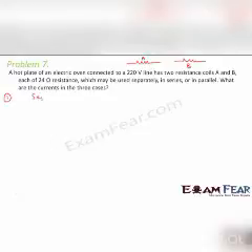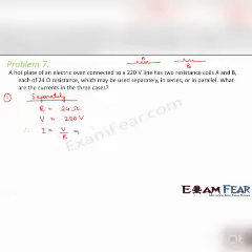The first case is when you use them separately. The net resistance is 24 ohms because only one of them is used at a time. The voltage is 220 volts. Therefore, in accordance with Ohm's law, current will be equal to V by R, that is 220 divided by 24, which is equal to 9.166 ampere. This would be the current when they are used separately.